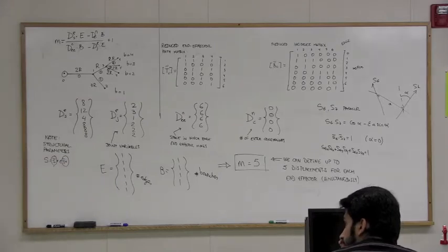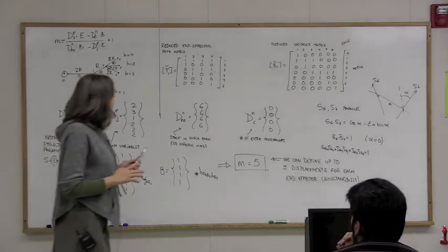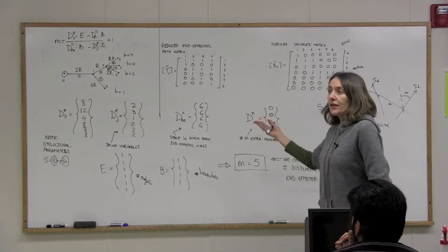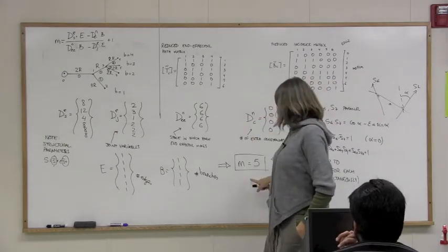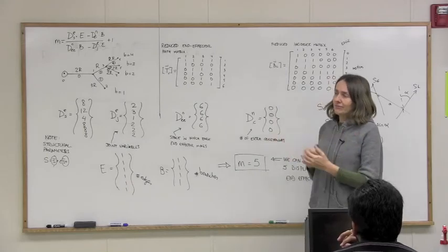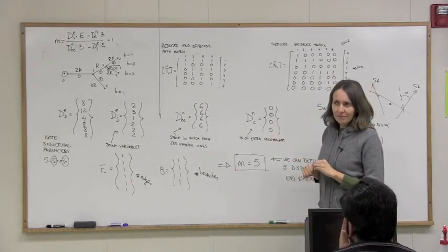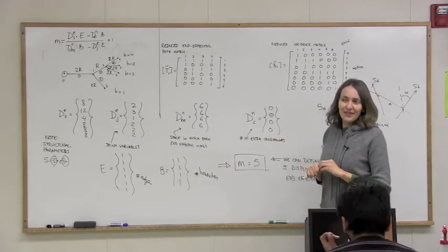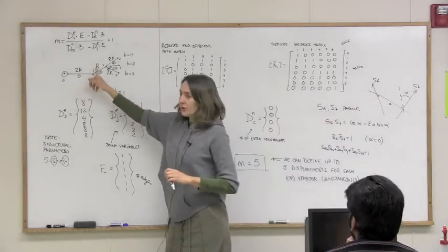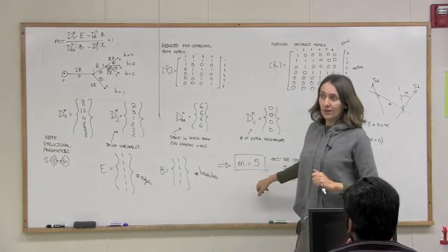So is that by coincidence that we got the 5 R's? Well, yeah. The branch will have 5. Yeah, so in general, if you have a 5R, the number of positions for a serial chain is more than that. It's, what is it, 21, right? It's a lot. I think it's 21. So just the fact that some of them are common reduces your number of positions.